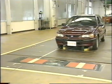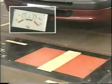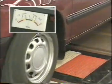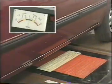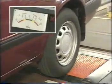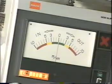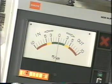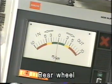Drive the vehicle slowly in a straight line onto the side slip tester. Then read the side slip indication as the wheels cross over the tester. Side slip is the amount of sideways slippage expressed in millimeters per 1 meter of forward motion. If the side slip exceeds the limit, camber and toe angle may not be correct. If so, another inspection is needed.